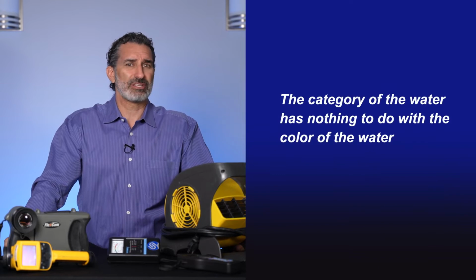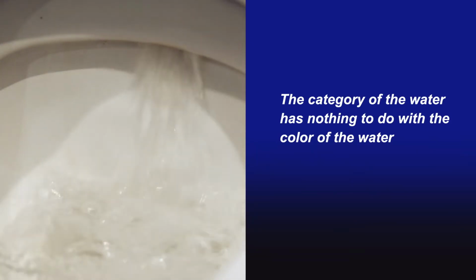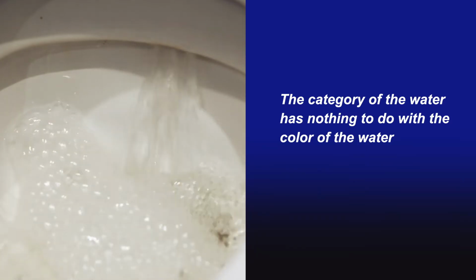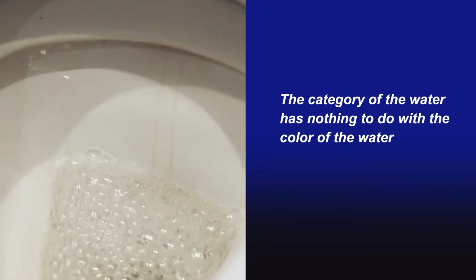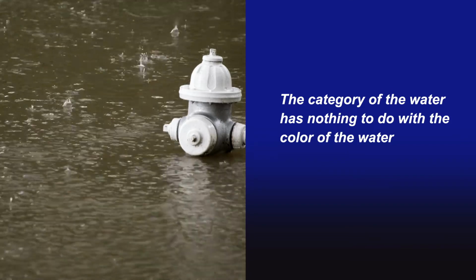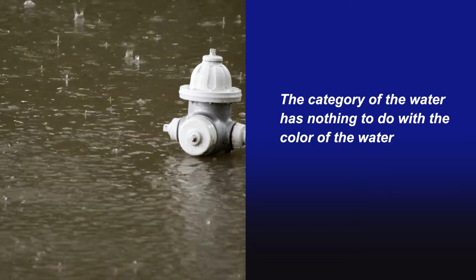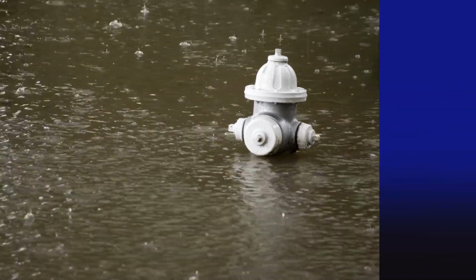look discolored. The category of water has nothing to do with the color. Water can appear very clean and be quite hazardous, and water can appear quite turbulent and be relatively safe. It's not about the color of the water. It's about the origin and what it came into contact with and how long that water has been sitting.